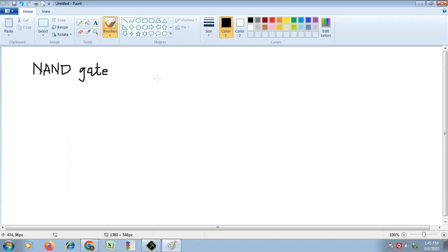Okay. So what is the equation for the NAND gate? Output Y is equal to (A dot B) bar. Correct? This is the equation of the NAND gate. Now, first we will draw the stick diagram of the NAND gate also, and from the CMOS design, we will draw the stick diagram. So first we will design this NAND gate using CMOS.